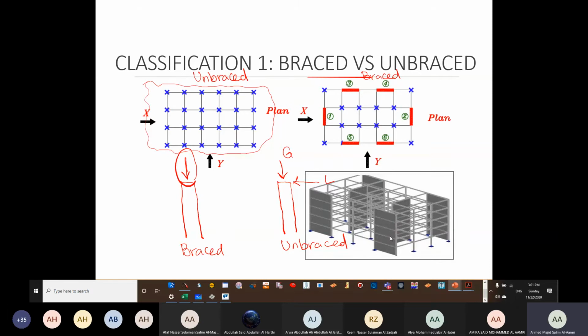So since the shear wall is there, these columns are going to be designed for gravity loads mainly. And when it comes to real construction, if your building is three stories or lesser, the lateral loading, whether it's wind or earthquake, the effect of these two loadings is not that much. So in this scenario, the column is not having a major load in case of lateral loading, so we don't need to take it into account.